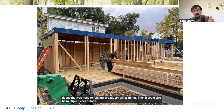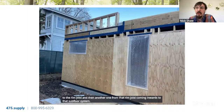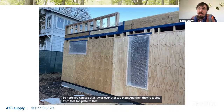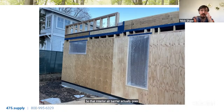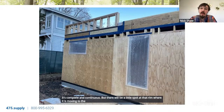One piece of tape over the top plate, one from that outer edge of the top plate to the rim joist, and then another one from that rim joist coming inwards to that subfloor system. So here you can see that it was over that top plate, and then they're taping from that top plate to that rim joist, and then they're turning that in and taping to the subfloor there. So that interior air barrier actually goes from the inside to the outside and back to the inside. It's complete and continuous, but there will be a little spot at that rim where it is moving to the exterior side of that floor system.